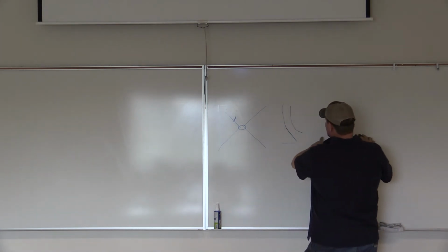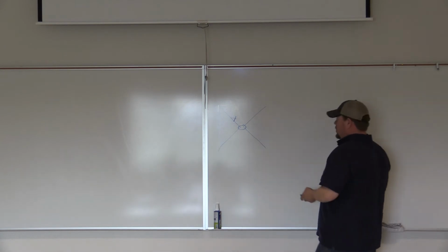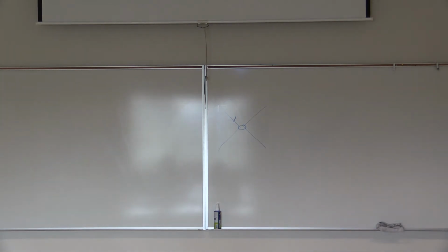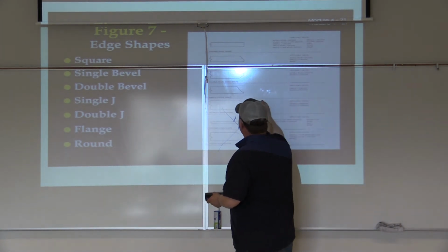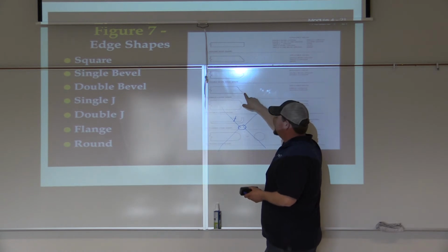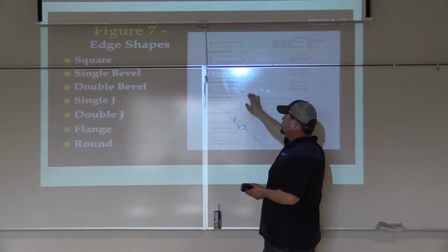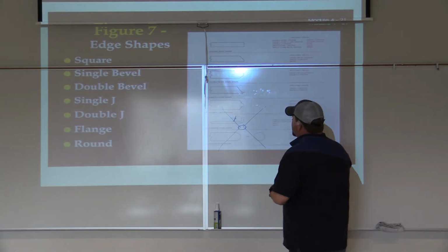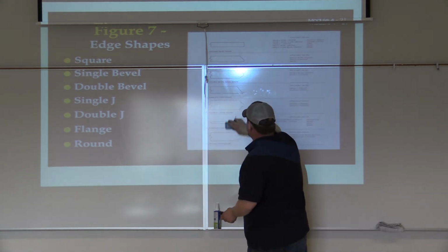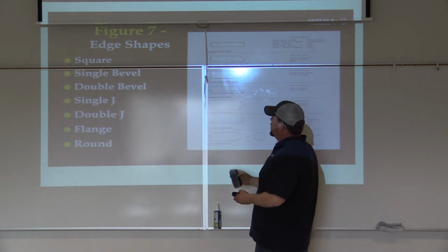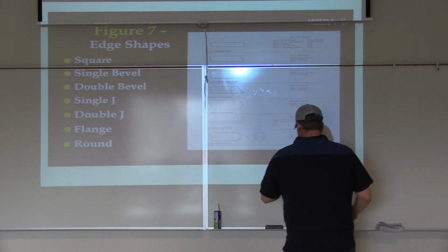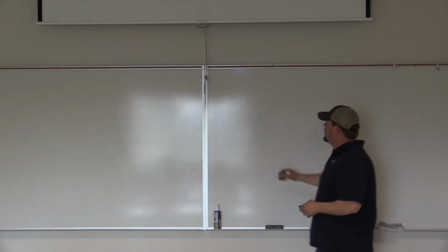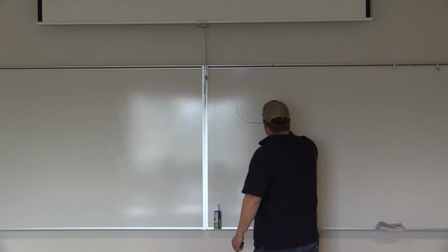And so in this case, it's a double J. On two sides, just a single, or in this case, it's a single J, but two pieces are with a single J instead of a double J as well. There are some cases where you'll get a spacer on a double J. The reason I say that is because this can sometimes be a consumable insert on a TIG.